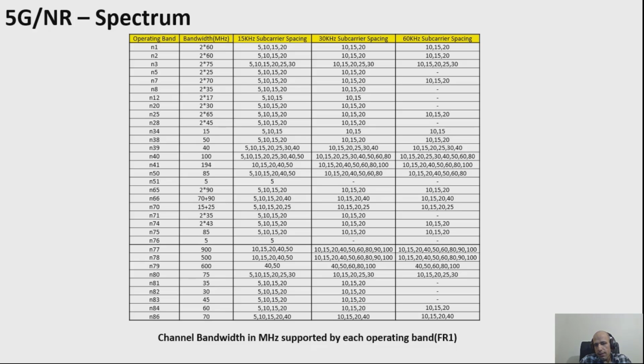Okay, in this case, the base station would recognize the UE capability and allocate resource blocks within its 20 MHz bandwidth. Different UEs could use different 20 MHz sections of the base station channel. A UE which supports the 100 MHz channel bandwidth could be allocated resource blocks from any location within the base station channel. In some cases, uplink and downlink channel bandwidths are not equal.